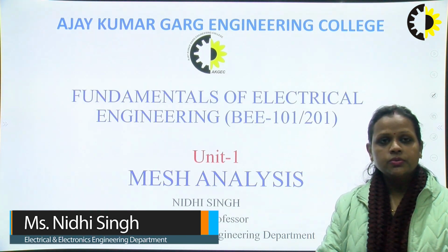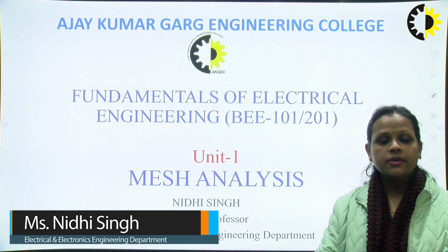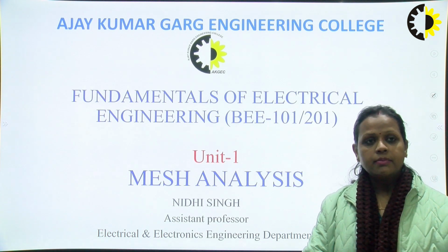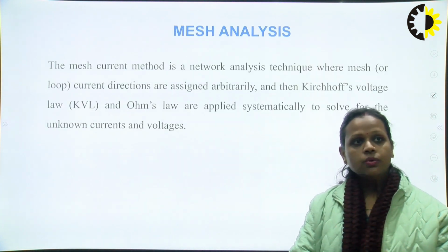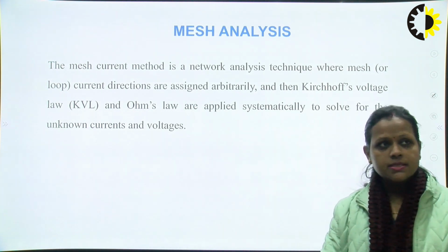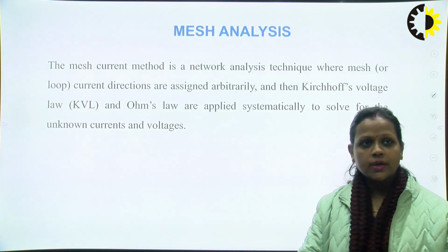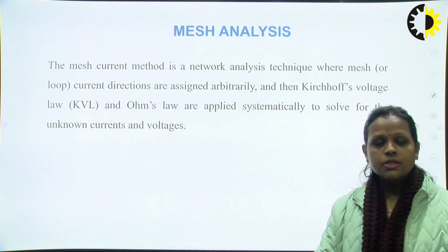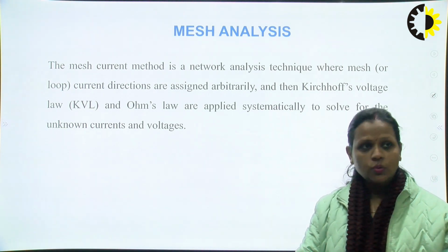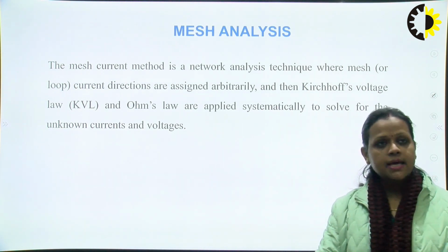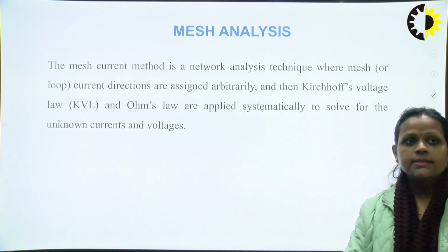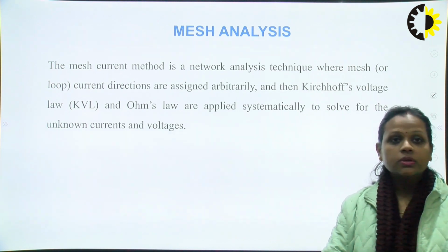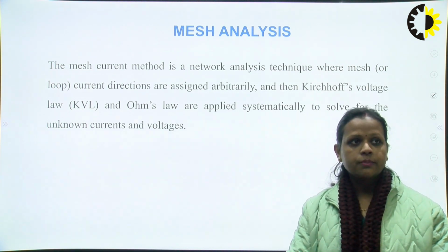Today I am going to discuss a topic from Fundamentals of Electrical Engineering, and I am discussing mesh analysis. This is a topic from Unit 1. So, what is mesh analysis? The mesh current method is a network analysis technique where mesh, or we can say a loop, current directions are assigned, and then Kirchhoff's voltage law and Ohm's law are applied systematically to solve for the unknown currents and voltages.